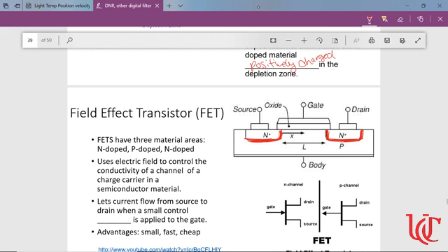So if I have negative charges build up right here on my p-type, then I don't want to send an electron from here all the way through from my source to my drain, connections to these transistors, because when it hits this negative charge wall, it's going to repel and send it backwards. So it prevents current from flowing in its default state.